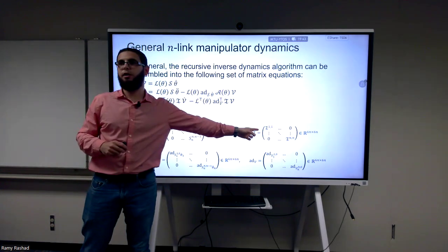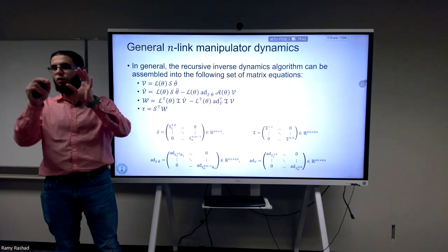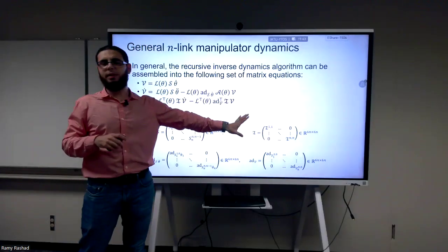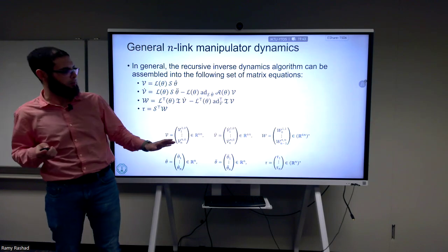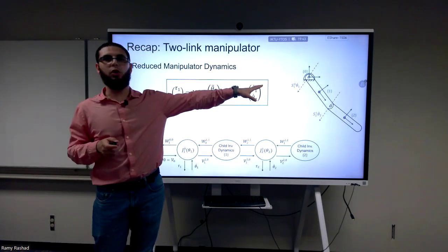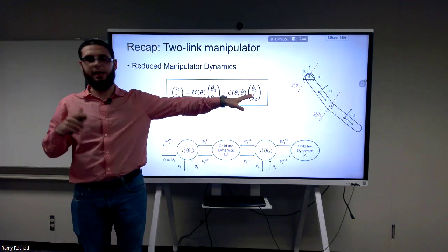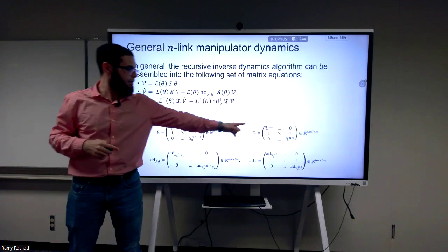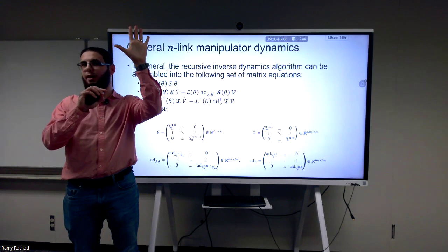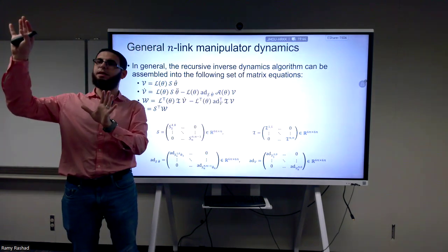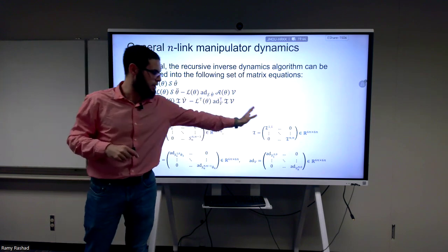This is the collection of all of the inertia matrices, the generalized inertia matrices that have the moment of inertia, the rotational inertia, and also the masses. We assumed here, just to make things easier, that we put all of the frames at the center of mass, aligned in any direction. So we don't require them to be aligned in any particular way. In general, on the top left corner I will have a J part, the off-diagonal parts will be 0, and on the lower right corner you're going to have M multiplied by the identity in 3 dimensions. And you collect all of these.